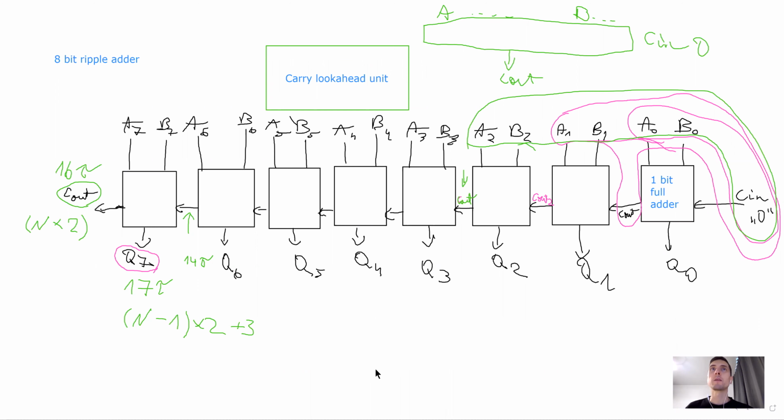But maybe, I think that in Logisim, it's possible to build this carry lookahead unit easily for something like 4 bits. And initial 8-bit processors built a simple carry lookahead unit for just 4 bits, and then another carry lookahead unit for the next 4 bits. It wasn't as fast as the theoretical maximum, but this thing calculated all carries in something like 2 taus, gives the result, and the next one after 2 more, and it's just 8 taus instead of 16 or 17 and so on. So it's possible also to build smaller carry lookahead units for some limited number of carry outs and carry ins, and just have multiple of them chained.